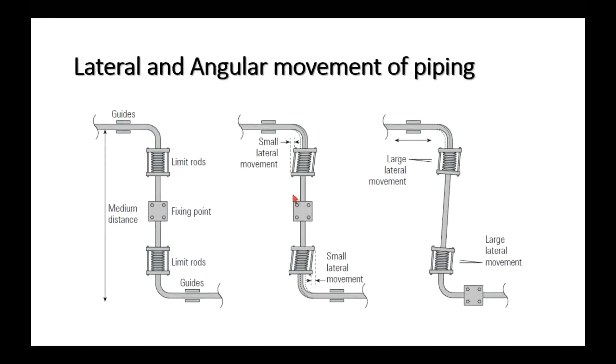Now, so here you can see we've got axial misalignment. And here you can see we've got angular misalignment. And so, one of the reasons that we have the guide and the anchor, everything can be installed correctly to prevent this type of stuff.